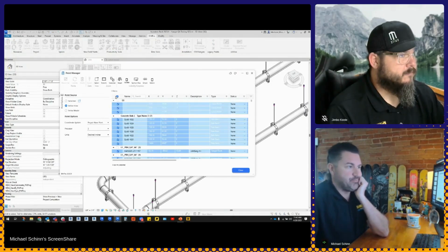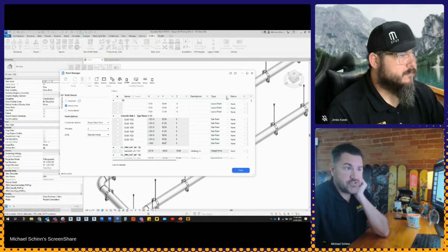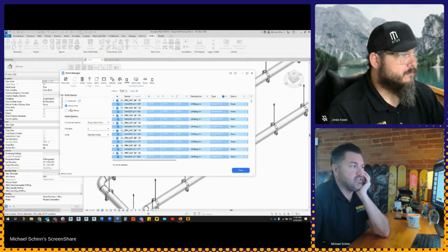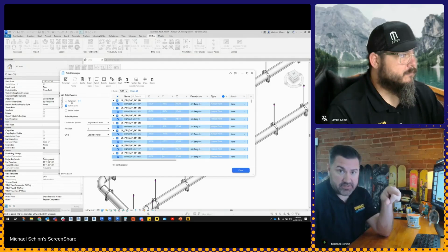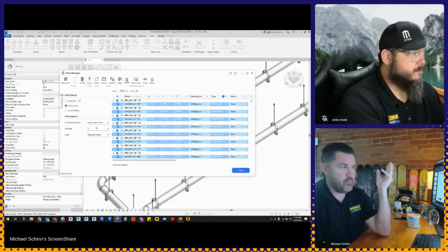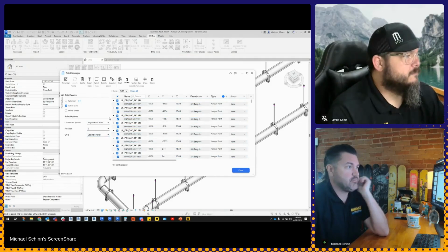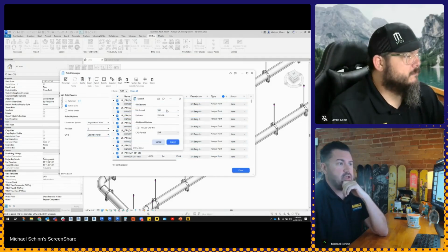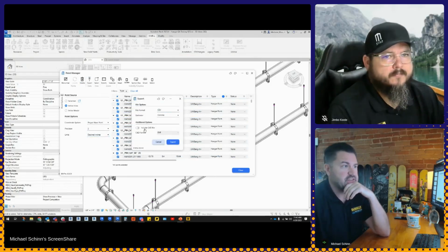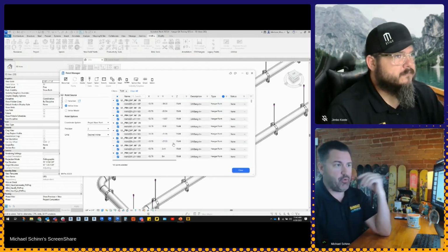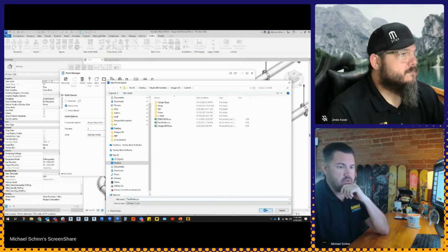I want to export out, let's actually just do our hanger points. Grab all the hanger points in my active view, maybe my only current selection of view or my entire model. What's my coordinate, precision, units? Great. Let's click export, and I can easily export this out to a CSV. Maybe also include a CAD file, a 2D view of this view as well. Click export, points are then updated. Click save.